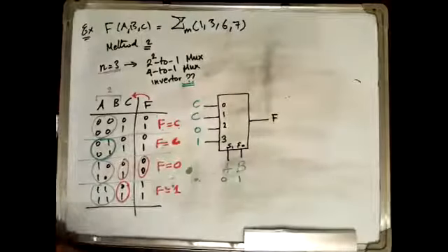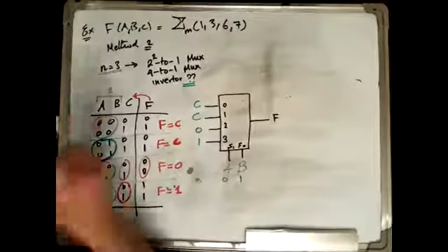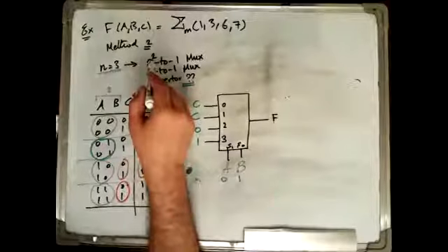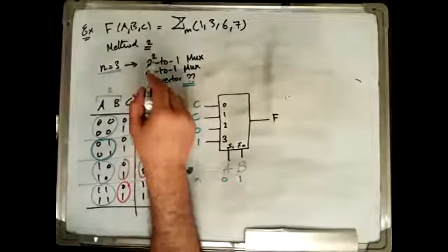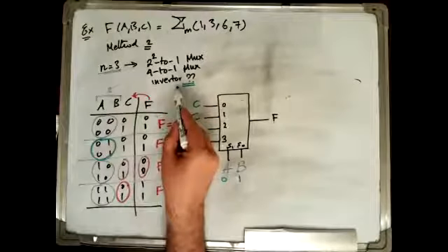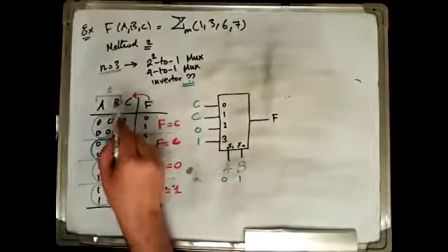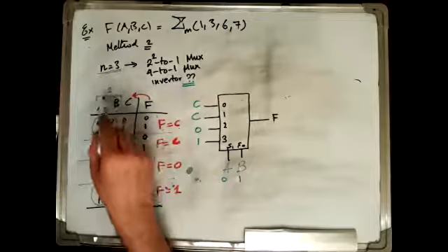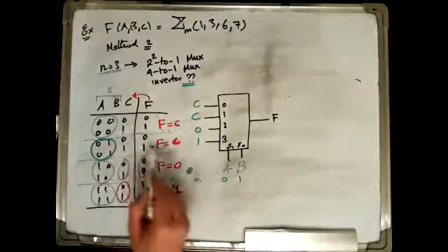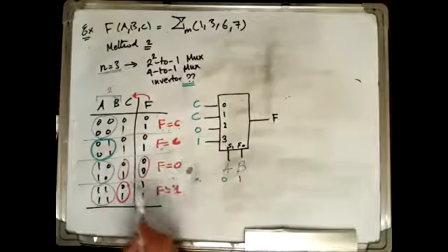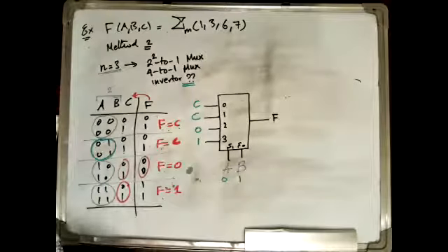So this is the basic idea. To use a multiplexer with half the number of inputs when compared to method number 1, we might need an inverter. And we need to split the table using the n-1 variables, as we did here. Then we specify the function in terms of the remaining variable, like what we did here.